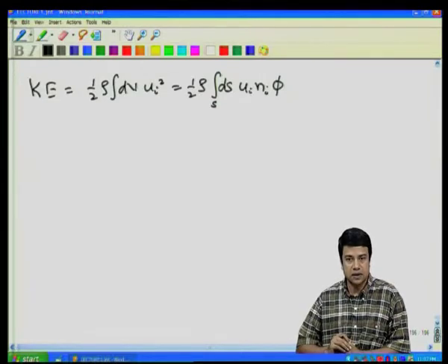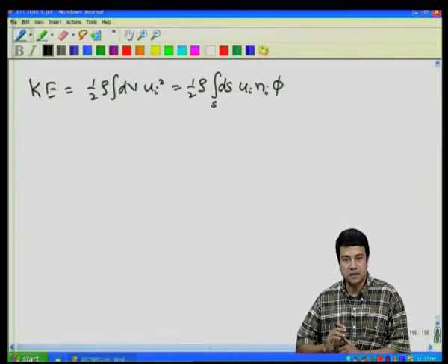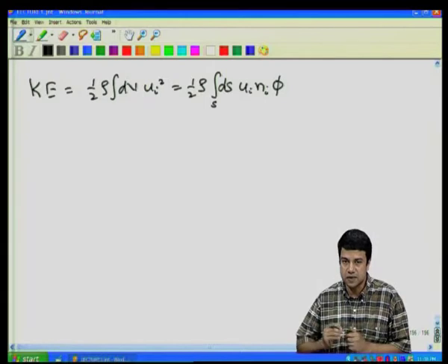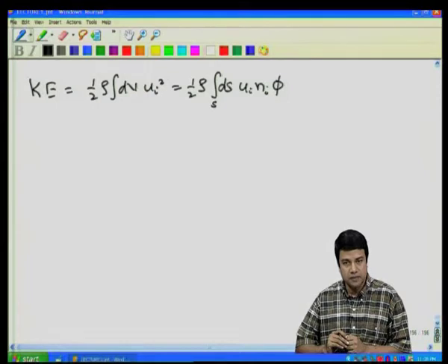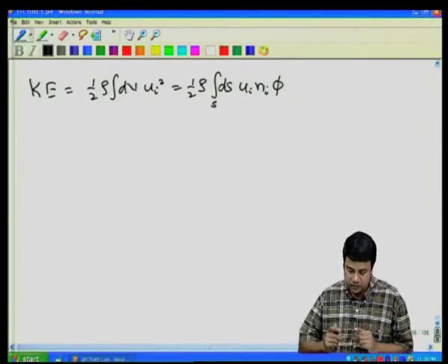We also showed that for a potential flow solution, the kinetic energy of the flow is smaller than the kinetic energy of any other flow, which does not necessarily satisfy the potential flow conditions. So, therefore, the potential flow has the minimum kinetic energy of all possible flows that satisfy the conservation equations, called the minimum energy theorem. And finally, we were solving the potential flow solutions for the flow around a solid object. As usual, we take a sphere as the simplest solid object, because we can use tensor symmetries in order to determine the velocity profile of the sphere.